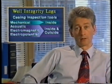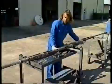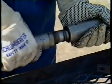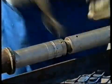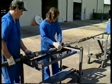Some of these, especially the mechanical tools, are used to inspect the intermediate strings of pipe for drill pipe wear resulting from deeper drilling. All of these tools are likely to be used to examine the casing in the producing interval for evidence of corrosion or deformation. The casing inspection devices used to inspect the production string are all too large to be run through tubing. Similarly, most of the cement bond tools are too large to be through tubing devices. But since the usual application is to run these tools before installing the tubing, size is generally not an issue.